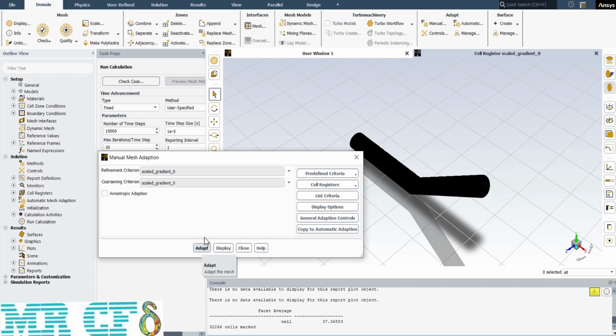As shown in the console part, at first the cells were about 200,000 elements, but after adaptation it gets to 433,000. Furthermore, in this case, the pipe experiences a shock wave, so there is an extreme pressure gradient, and you can define another criterion, for example, solve the case in a steady state simulation and then determine where the gradient changes and the range of pressure. Then define a gradient adaptation for pressure in a specific range, and continue the simulation with the refined mesh.